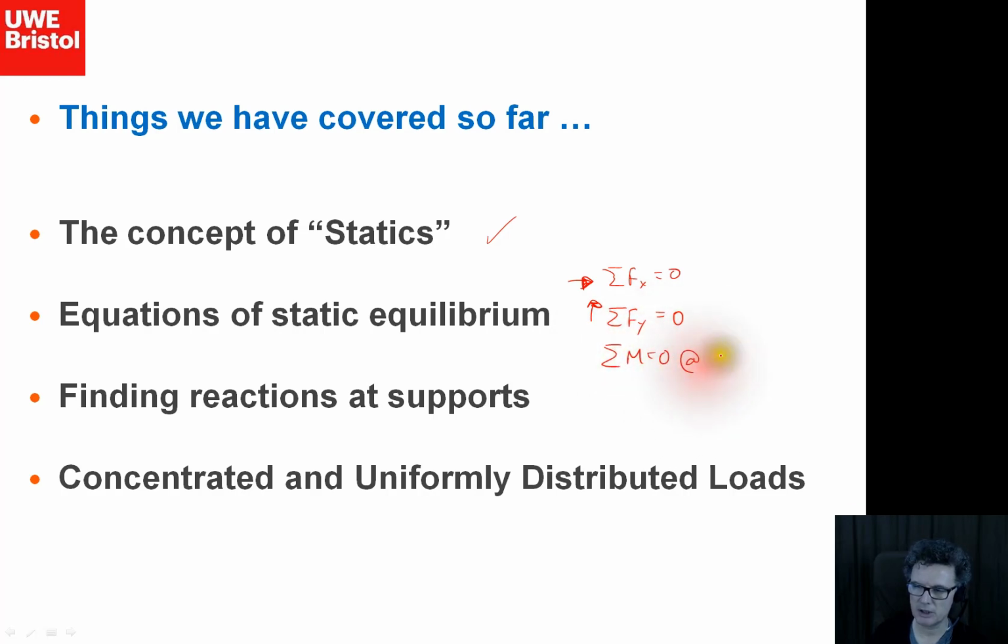We can take moments anywhere we like, so some logical place that we choose on the framework, usually that's convenient to measure distances. Typically that will be a joint. Finally, we can work out the reactions at support, so we'll go over that again.